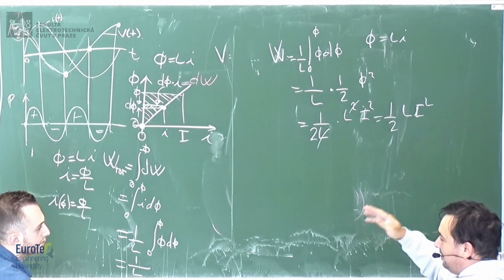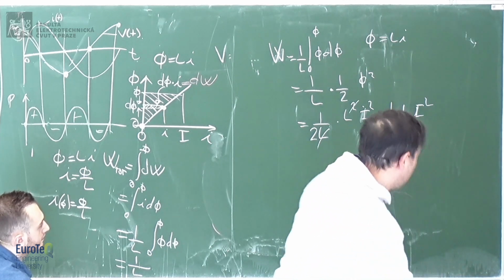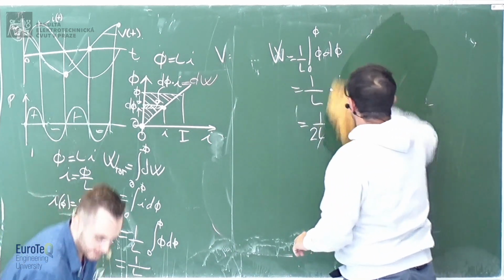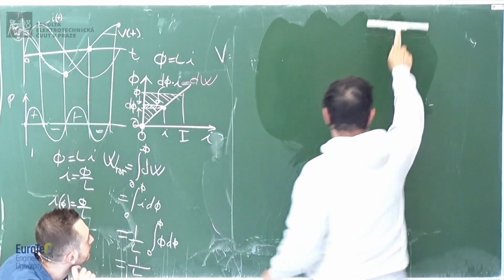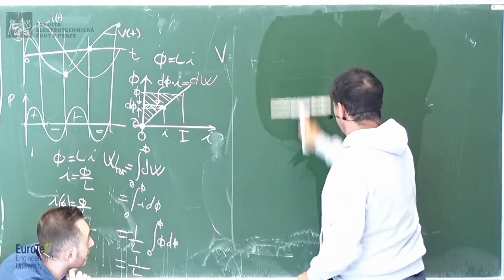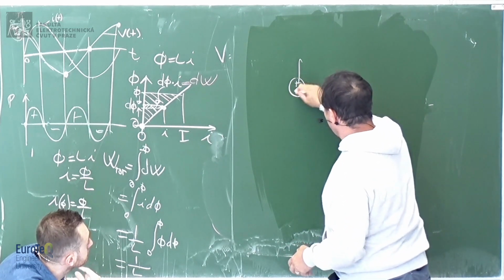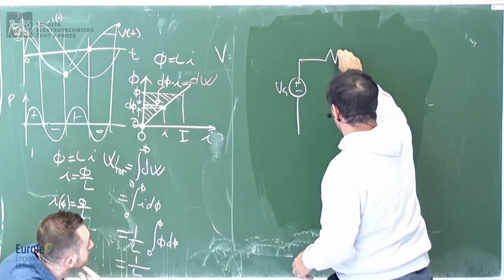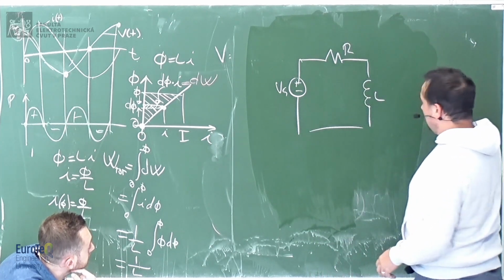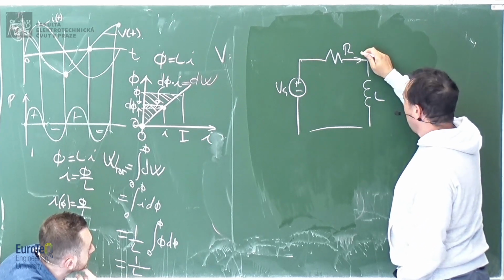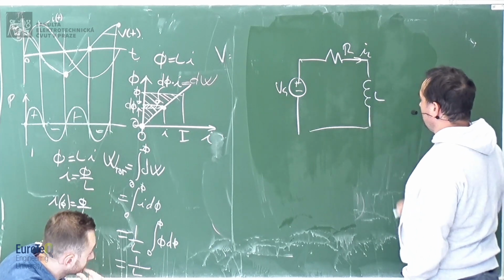Let's say that we have an inductor which is already at steady state. So there is some current running. Well, yeah, now that it's in steady state, it's basically a short. Okay, yes. So you have our source, you have our inductor. The current is already the maximum current. So here the current of the resistor is the same as the current of the inductor.